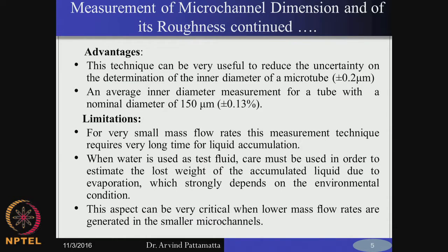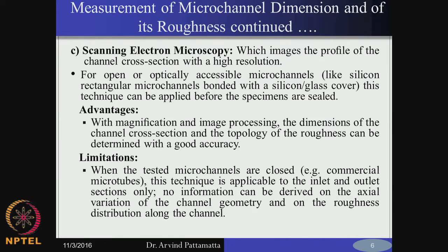So, again, that will be causing some errors in the difference in the weight. Especially when you are talking about smaller micro channels, these losses due to evaporation and so on might affect the diameter measurement to a great extent. Okay. But nevertheless, this is a better method than simply weighing the channel itself.